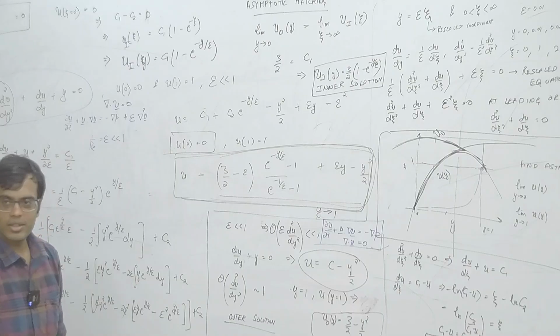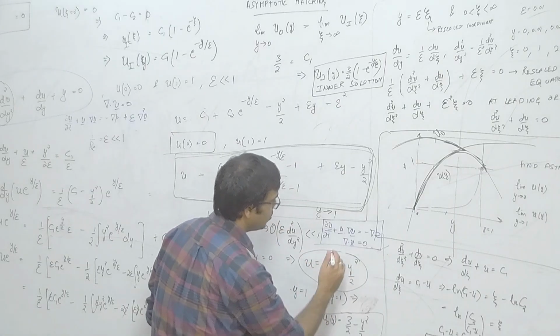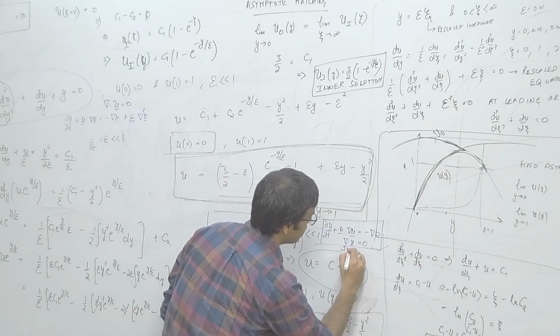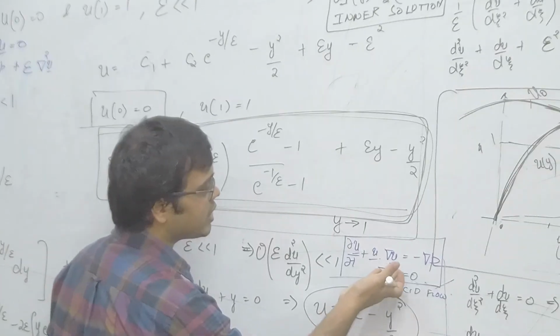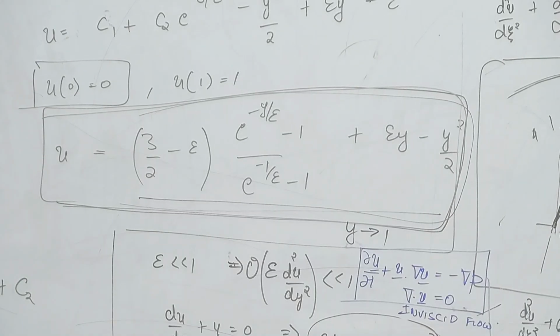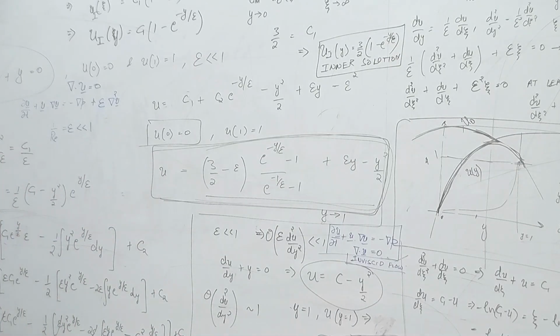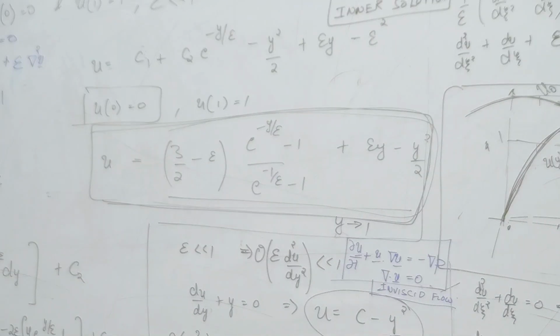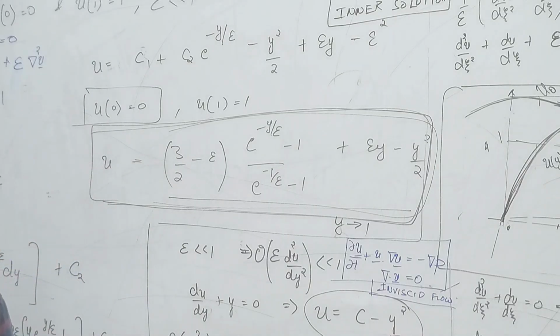This was not done in your introductory fluid mechanics course, I mean inviscid flows and ideal flows, no? So this is the inviscid flow equation, technically inviscid incompressible flow. And the idea is that inviscid flows technically are not flows of fluids which have zero viscosity, except for fluids which display quantum behavior such as supercooled superfluid helium. There is no fluid of practical interest which has zero viscosity.